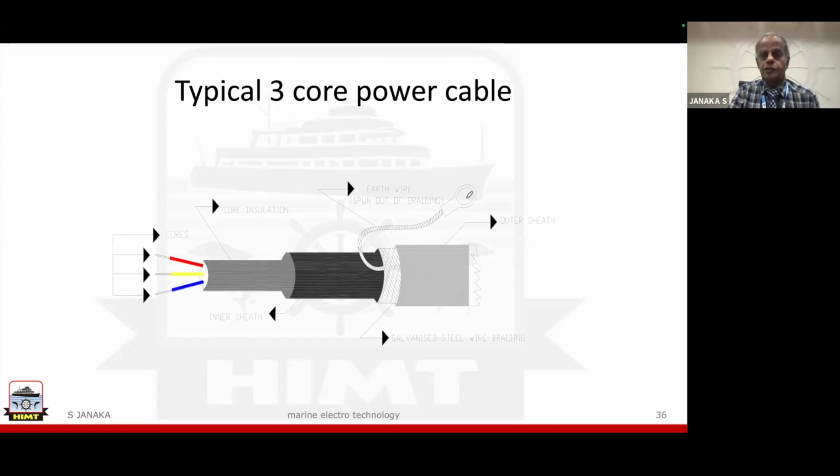As per IEC recommendations, it is preferable to have this grounding every 4 meters, so that operating personnel are safeguarded against these static discharges. By chance, my body is wet and I'm touching this cable. If I don't have the proper earthing, the static discharge may take place through my body. So these types of safety precautions are given, which we have to strictly follow.